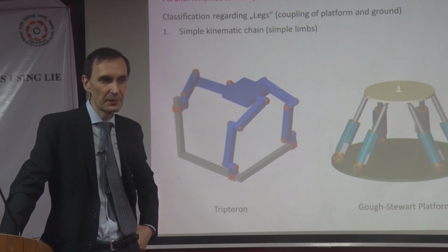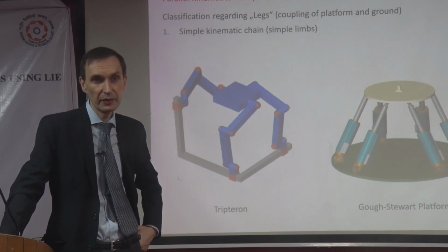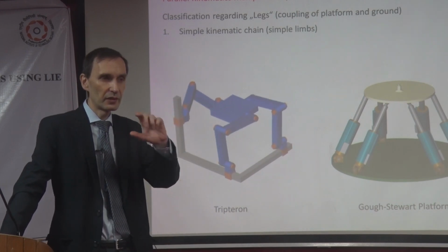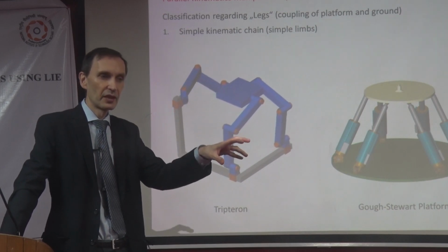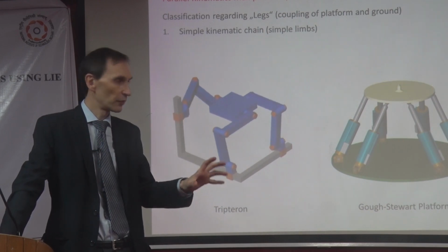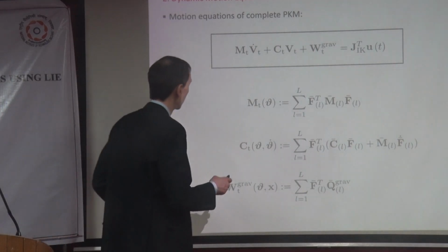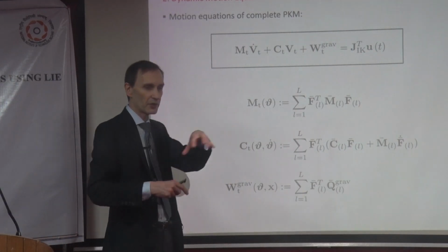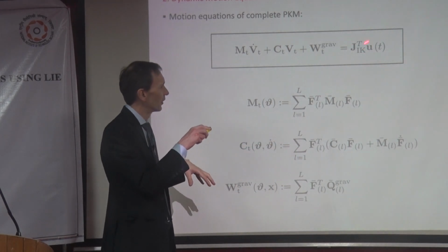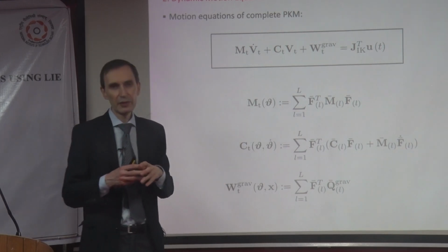Eventually, these model-based control schemes all do force control, at least the feed-forward part of force control. And remember that we had the equation of motion, so there are two uses for it. One is the one that we use in control, which is the feed-forward control. So for the PKM, you would prescribe the motion of your platform, and then what you get out is the input forces that you need. But of course, only if everything is correct.